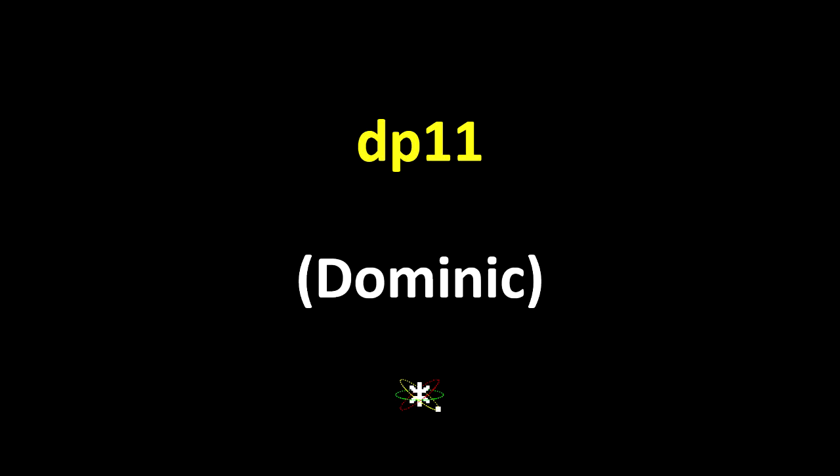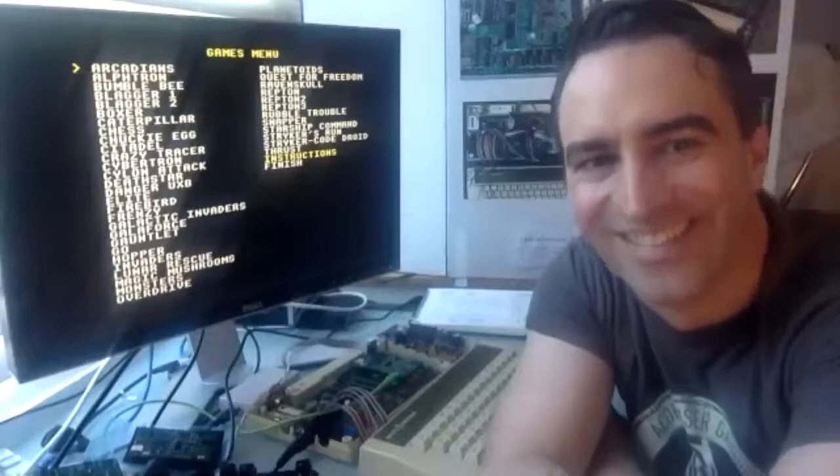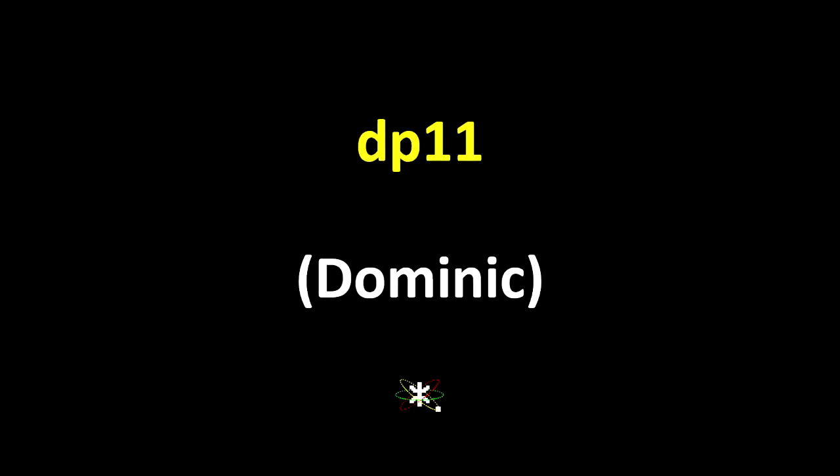So if you effectively make a DAC, you can use the DAC and the input cell as a comparator to form yourself a little ADC, and then you can just track your signal. That's really clever. And again, it's literally only a few lines of Verilog to do that.